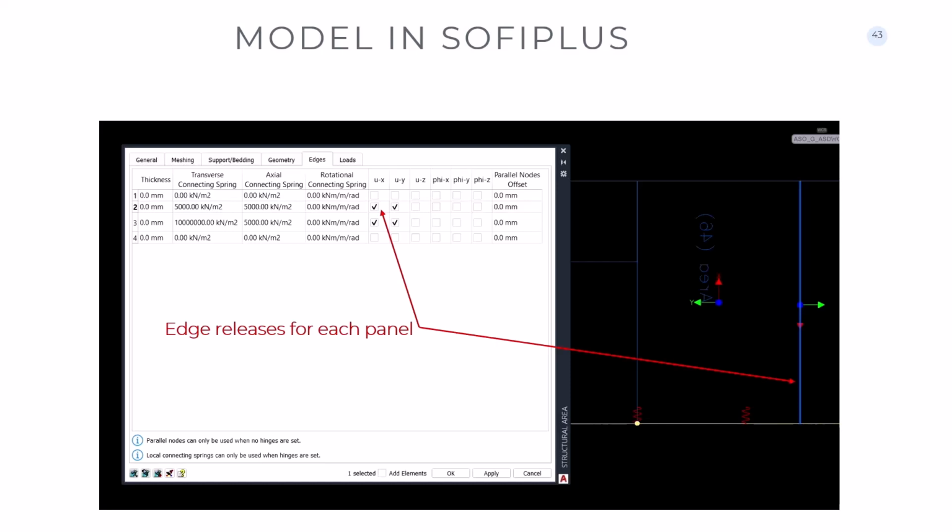The reason behind that is that every time you fix timber to timber, you use either a screw or a nail, and this nail has, according to Eurocode, what is called a slip modulus. The way that the screw works is that it's able to give you the resistance you're asking, I don't know, 3 kilonewton shear capacity of the nails, but this will happen with the nails deforming themselves in a sort of S-shaped curve. So you get that by a sort of slip of one surface with respect to the other.